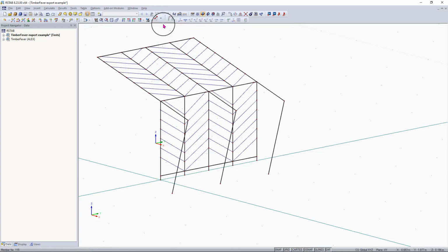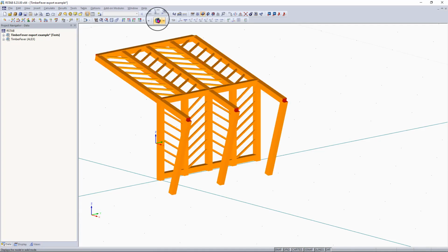And you'll see this is basically the reason why we needed those center lines from Rhino, is because members within RSTAB are basically just 1D member elements, and the cross-section properties and material properties are embedded within these 1D elements. And these renders that you see are simply just that. They're just renders for aesthetics, basically.